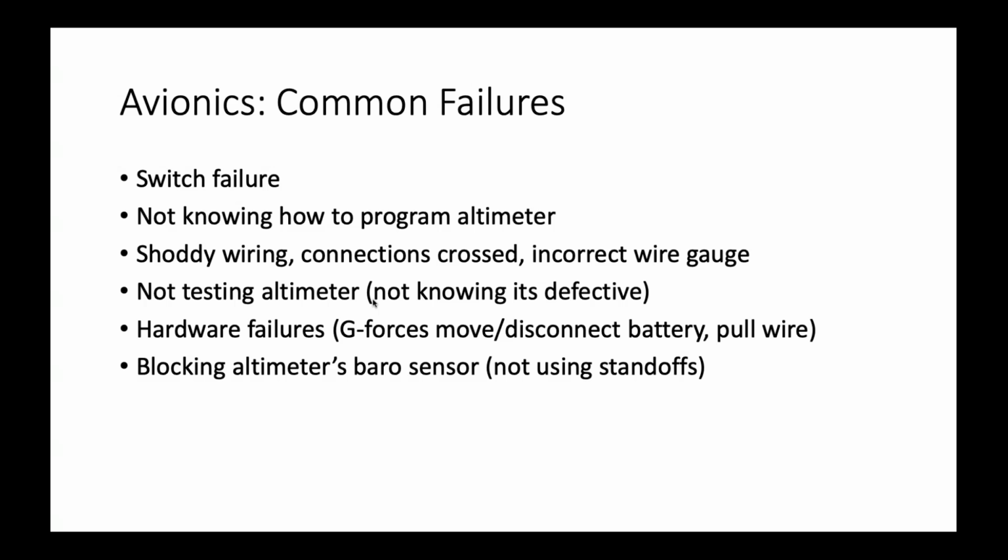And another one, the altimeters measure altitude by the barometric sensor, which you probably know, but sometimes it's on the bottom. If you're using a plywood plate or another kind of mounting surface, sometimes if you screw the altimeter board right onto that surface, it will block that barometric sensor.